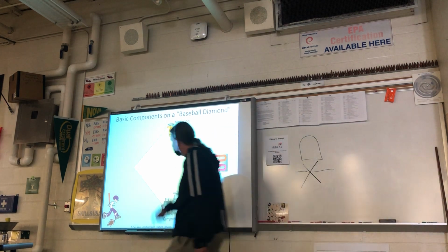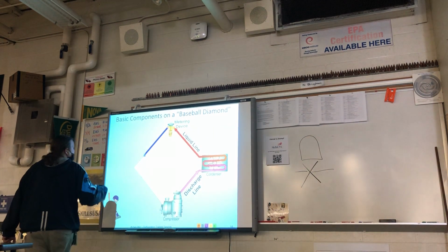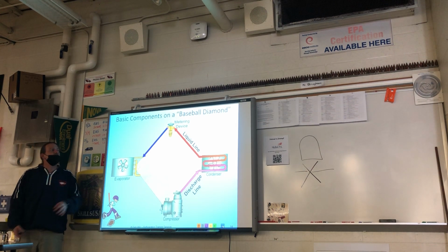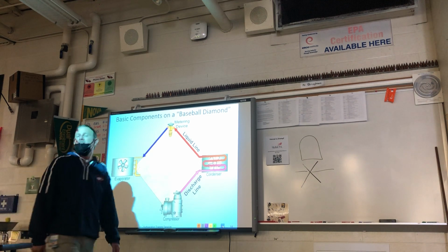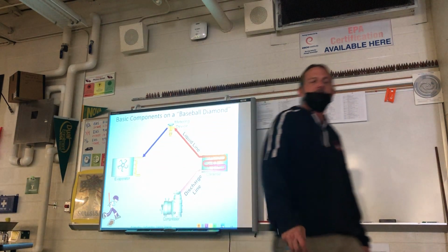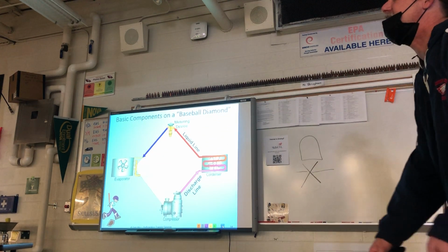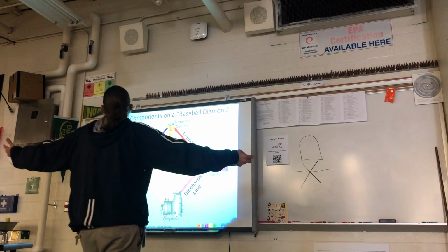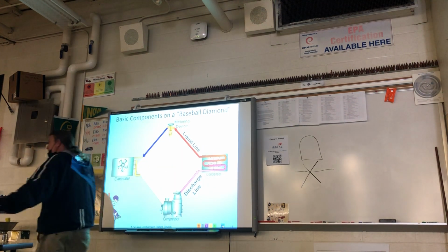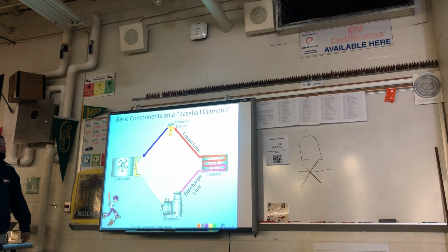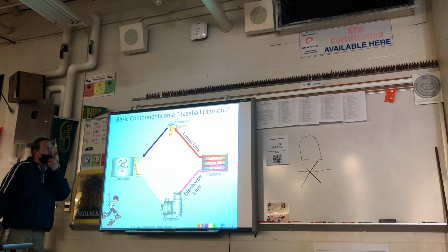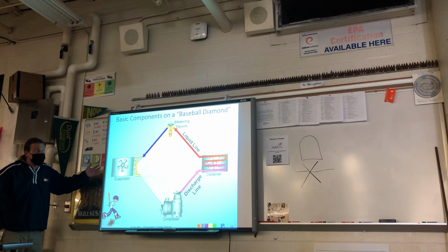But this line here is not listed in any of the books, but it's an expansion line. Because that's what happens. It's like if there were 10 of you in an elevator and the door opens up, and you guys got to come out together, tightening up even, first thing you're going to do is expand once you get to the open area. And that's what happens with the refrigerant as soon as it leaves this orifice inside whatever device we're using, whether it's just an orifice or a cap tube.